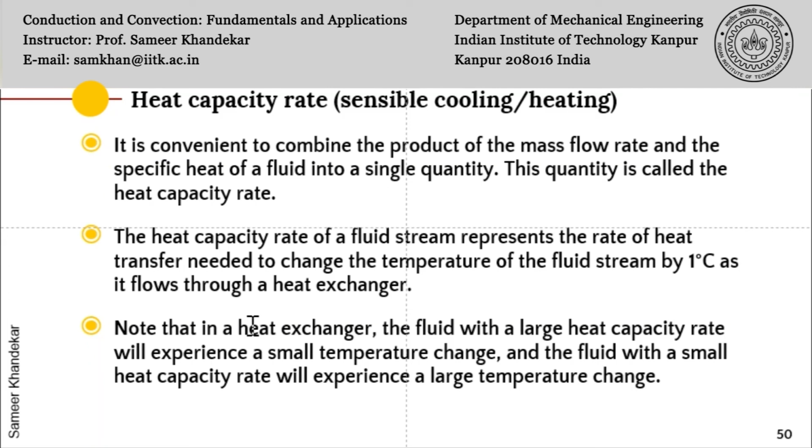So please note that as soon as you have a higher thermal mass, then it is natural to say that of the hot and the cold fluid, the one which has a higher heat capacity rate will have a smaller temperature change, and vice versa.